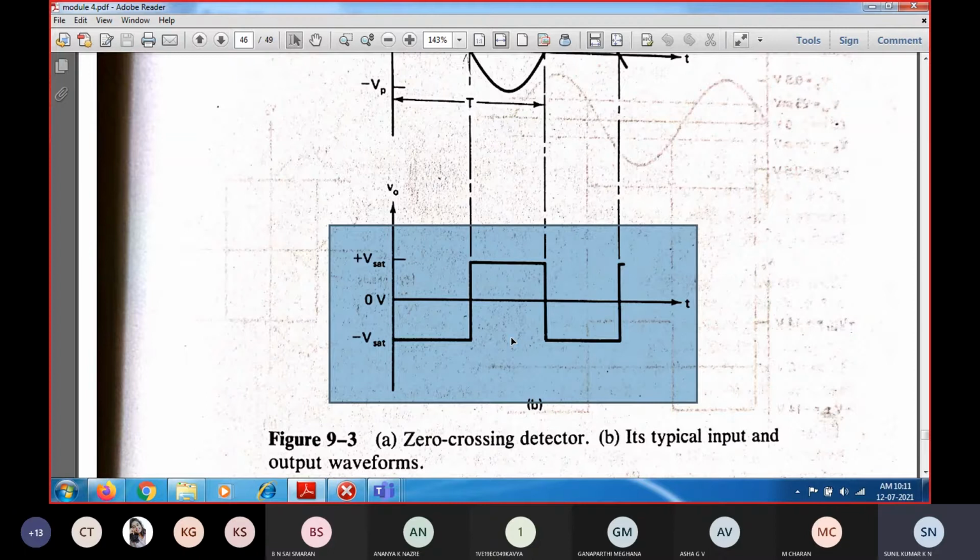Similarly, I have also studied various properties. Depending upon that, it is going to provide a sustained oscillation, and it is not going to vary with respect to temperature or with respect to any component value. Because it is a crystal, based upon the piezoelectric property, as I told, it is going to work and provide a sustained oscillation.